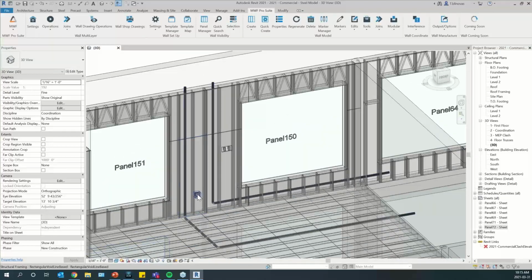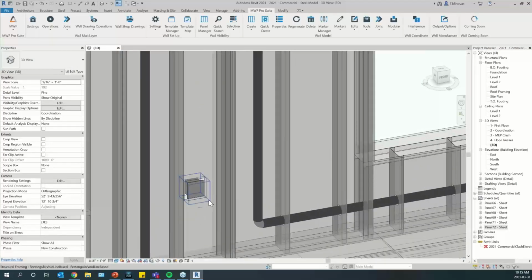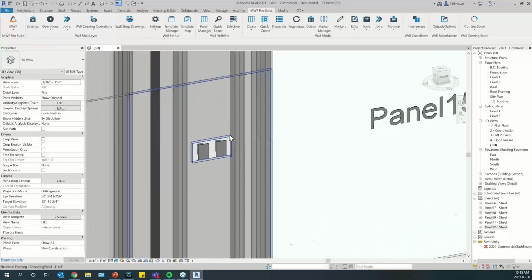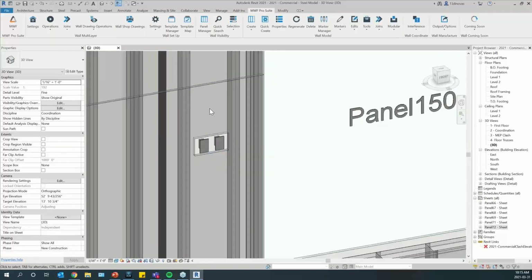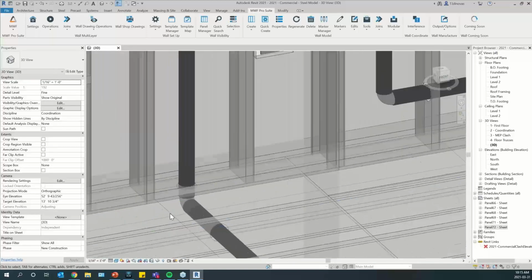And then if we zoom in, as you can see, it cut the sheeting around my outlet. Because I added a tolerance, those two guys here join in one big cut, so you wouldn't have to have two small cuts here. You can just merge them together. That pipe here was clashing with my bottom track.